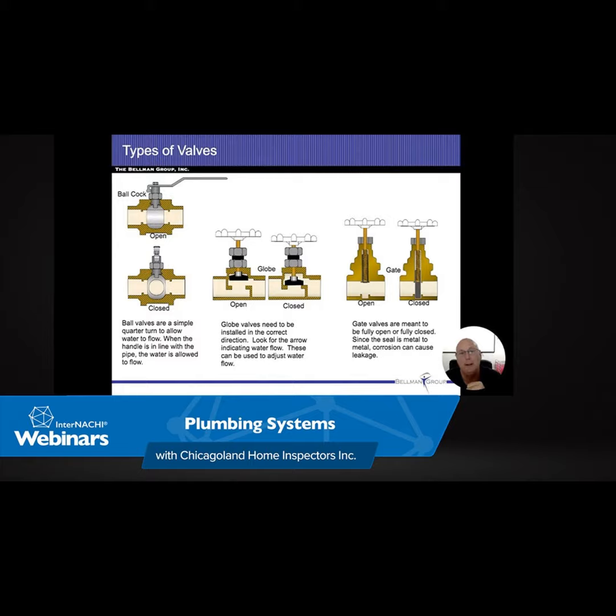If a water heater's in a garage, and this is more of an exterior garage thing, anything that has a gas appliance, the flames, or anything in a garage has to be at least 18 inches off the ground. And anything that is an ignition source, to be clear, has to be 18 inches off the ground.